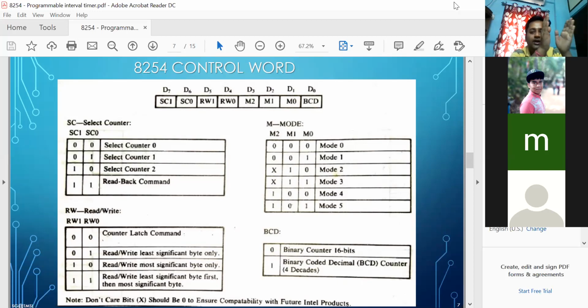So you have to ignore that bouncing period, so the microprocessor does not consider the noisy signal as input. Your input should be stable, either 1 or 0, not fluctuating in between. Clear? That's why the debouncing technique is used.